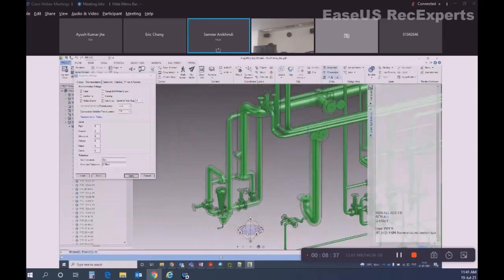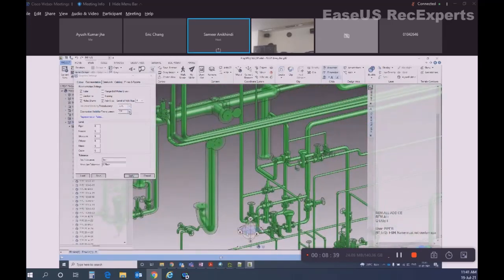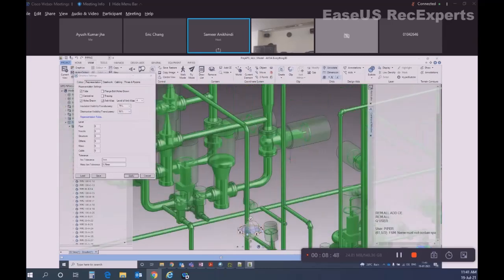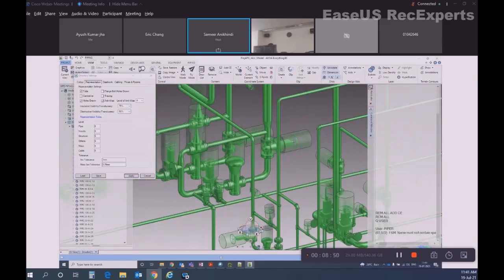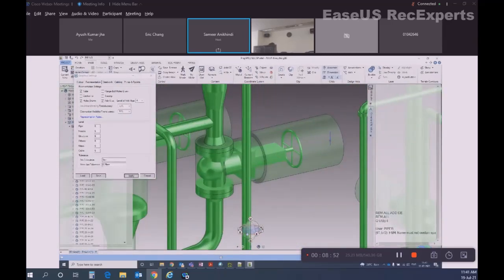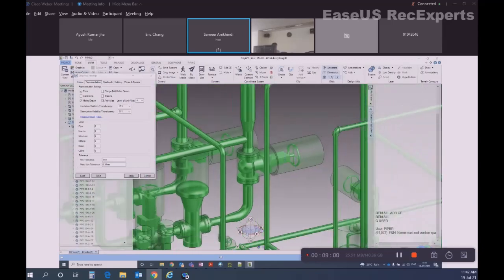Similarly, there is obstruction volume. Obstruction, let's make it 50. Apply. So it will show some obstruction volume, especially the walls and control walls. You can see the wall operator height, operator hands clearance, and some piston up and down clearance is given to walls.